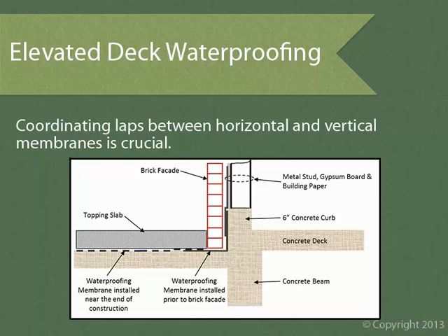So, since the facade and topping slab construction will undoubtedly take more than 30 days, we've got a problem with this sequence of construction. Secondly, exterior decks are always found to be good places for staging materials, setting up sawhorses, and any other type of construction traffic you can think of. These construction activities, materials, traffic, etc., will undoubtedly damage the membrane. To prevent this construction damage from occurring, we can follow a slightly different route.